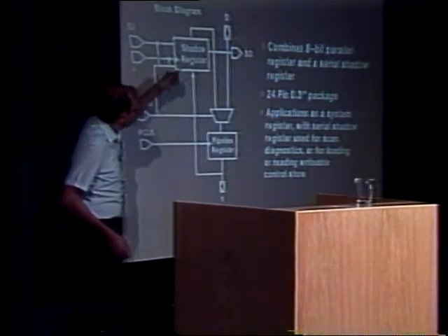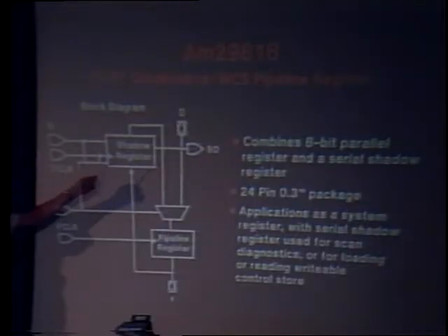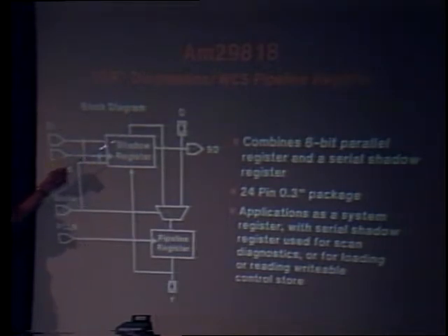Now, all of the other chips also have the same thing, but in addition to this serial shadow register, they would have, for example, the PROM here, or the RAM here, or the programmable controller sitting at this point. So there is still some way out. If things got left out at the chip level, you could try them at the board level.